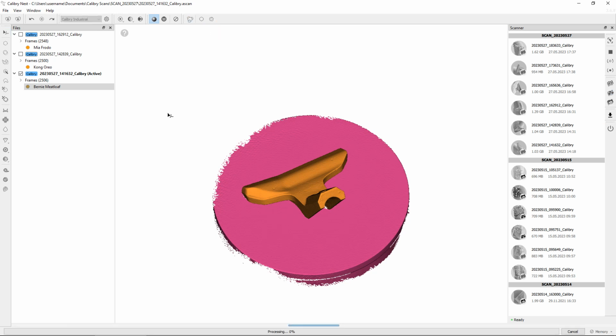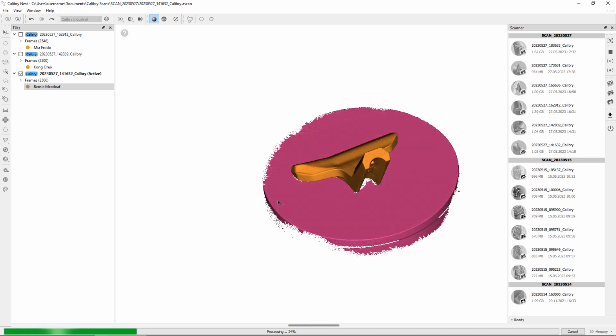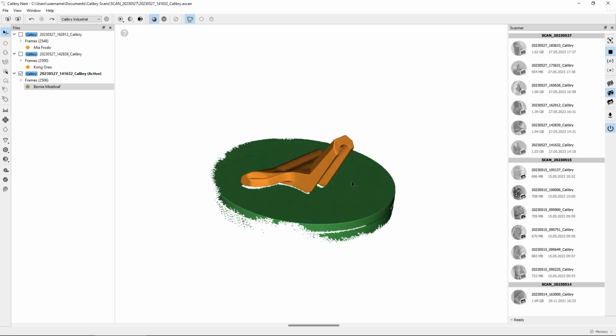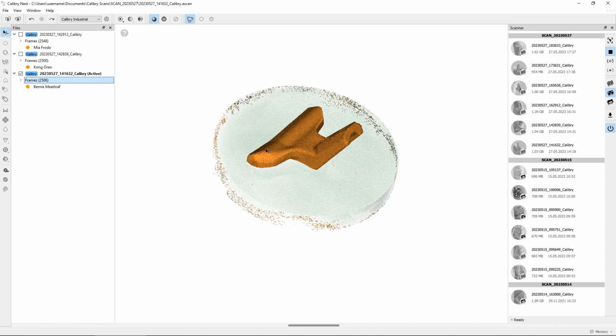So if I click on it, it just tries to calculate which points were used from the point cloud to make this surface and mark them as needless. So it's pretty much the same, but it just takes longer. So it is always better to do registration, then priority markup, and then finalize. But it's also possible to register, finalize, and then click priority, make a priority selection. But this is not optimal.